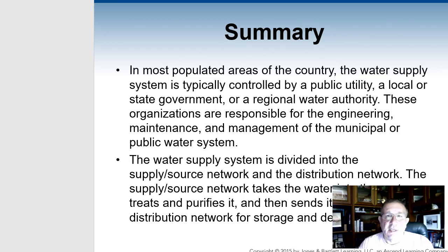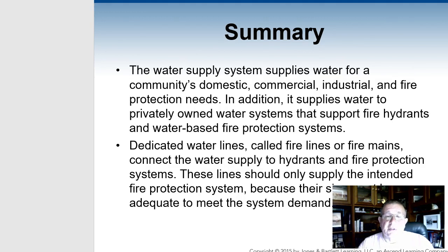Look at what the gauge says as far as what their intake pressure is. Also, hook a fire hydrant up to the fire truck and see what the pressure is that you'll get off the hydrant itself. Is there going to be enough water to flow 3,000 gallons a minute? Maybe not. So these are all key elements in the water distribution system.